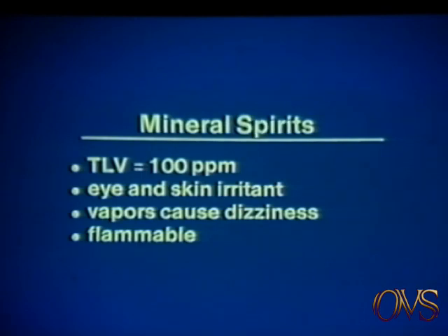As with other petroleum products, mineral spirits is harmful or fatal if swallowed. Wear eye protection, protective clothing, and gloves to avoid repeated or prolonged skin contact. If ventilation is inadequate, use an organic vapor mist respirator approved by NIOSH. The flash point for mineral spirits is 100 degrees Fahrenheit, so the liquid is considered highly flammable. Mineral spirits will float on water and will cause a slick.